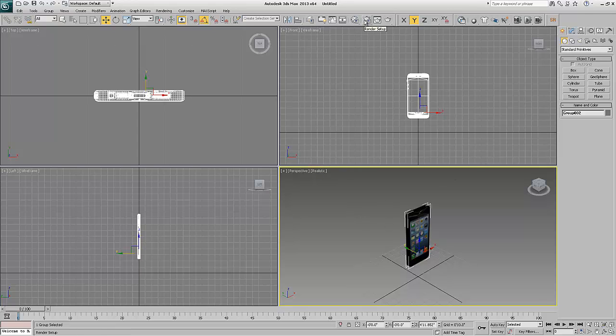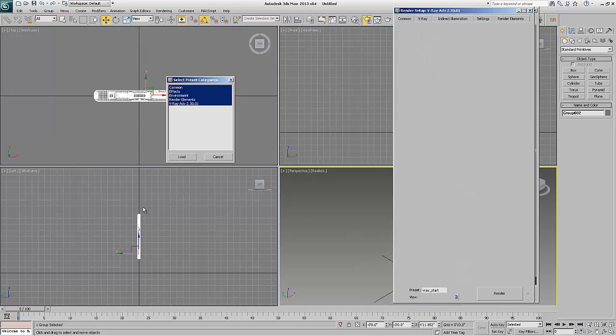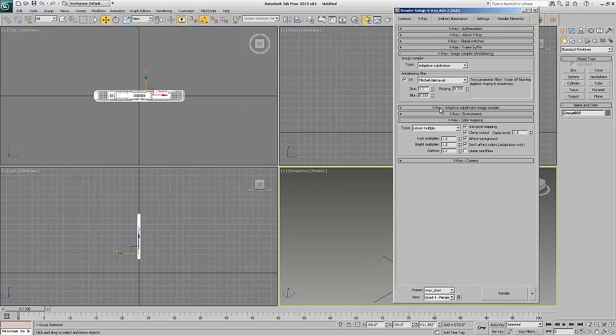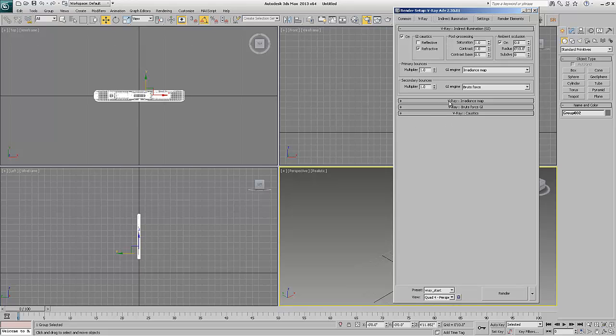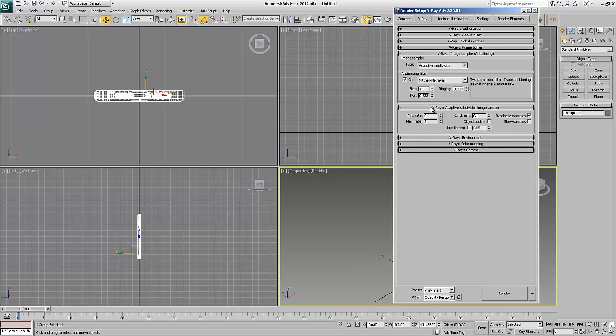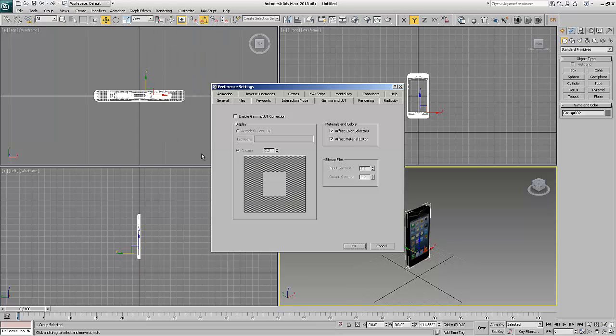So now V-Ray is already here, but I'm going to load my own settings, which is V-Ray start, and it basically sets everything up the way I like it. Linear workflow, all my settings to start out nothing high quality, just so I can move quickly and check renders. Next, I'm just going to make sure that the gamma control is on. It is not, so let's turn it on. I like the output at 1, but everything else like this.